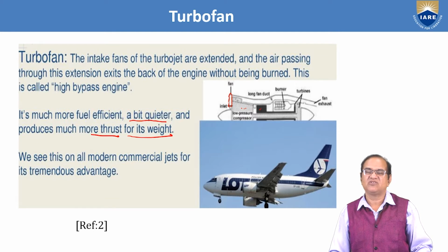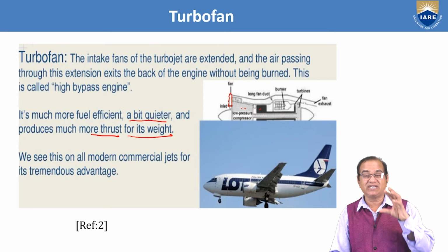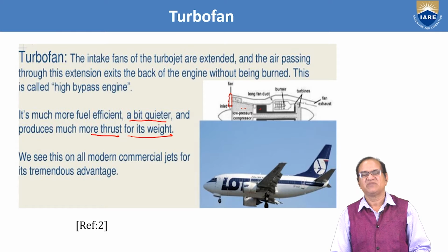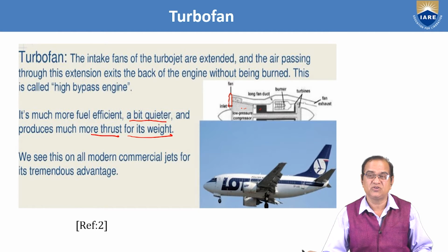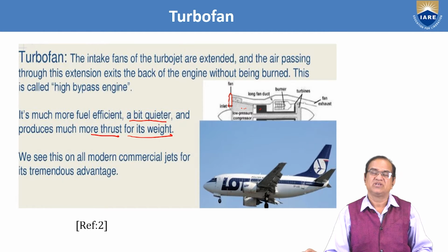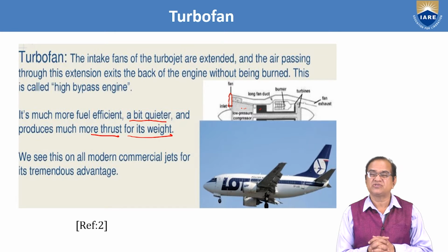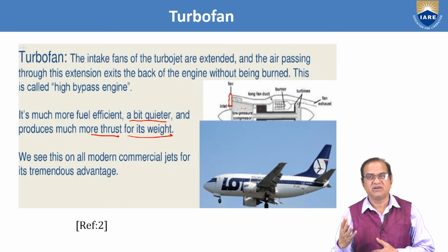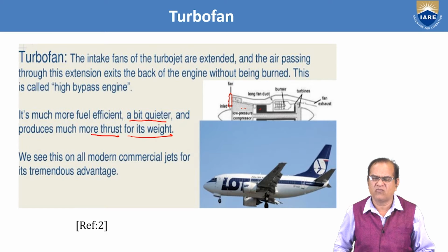However, nowadays fighter aircraft have also started using a medium bypass ratio turbofan engine, because size is reduced, weight is reduced, and the sound is also reduced. So like the Rafale engine and others, we use the medium bypass ratio turbofan engine.